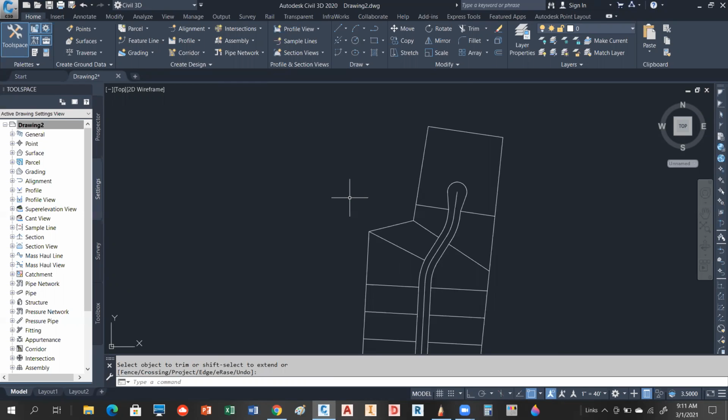Why do you have to hit enter twice when you're doing that trim command? Okay, let me get into it real quick. If you hit trim, enter once, it asks you to select objects to make boundaries from. By hitting enter again, you've made everything a boundary. So you can selectively make a boundary, or you can make everything a boundary. It's just a difference, that's all. Okay, thanks. Yep. All right, so let's go back and look at this picture.